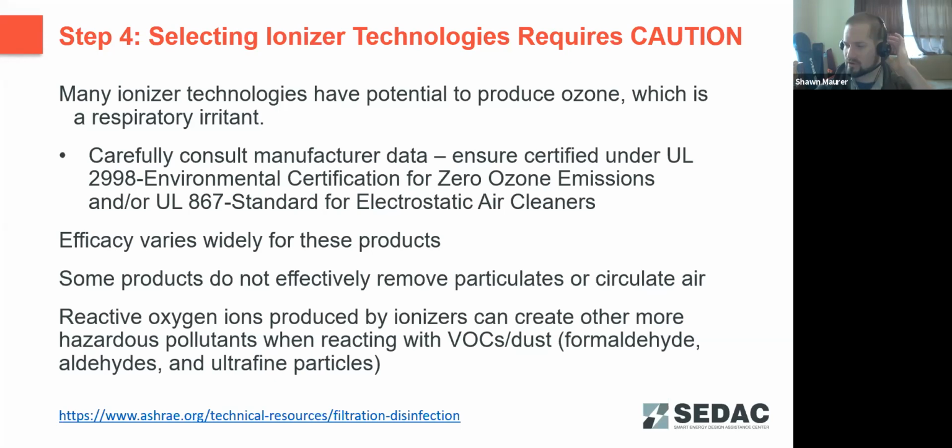Those don't have a very good clean air delivery rate, as they only clean the air immediately around them. So if you do opt for one of these systems, you want to set up some way to drive air through them. But I would recommend staying away from these low flow, quiet air purifiers, as they do have reduced efficiency.